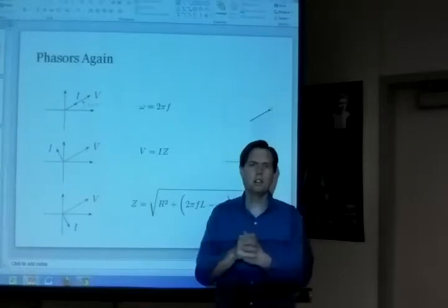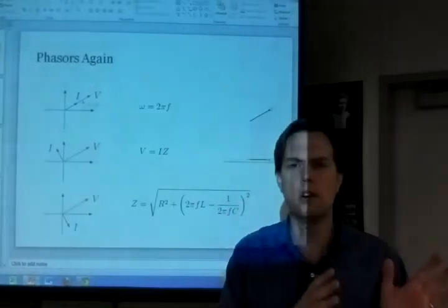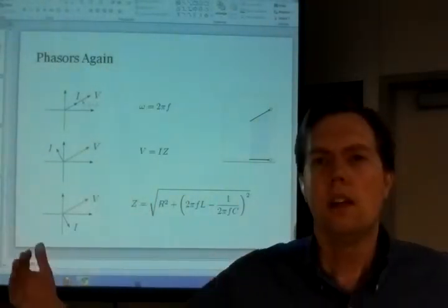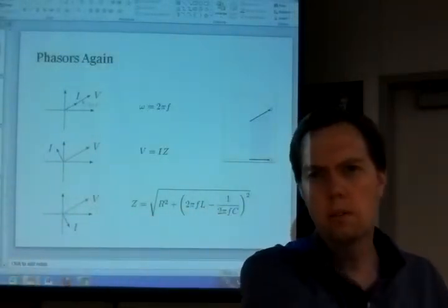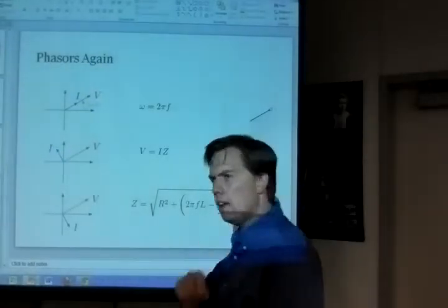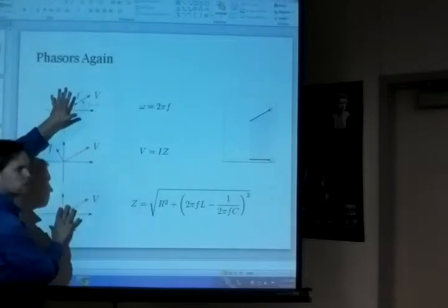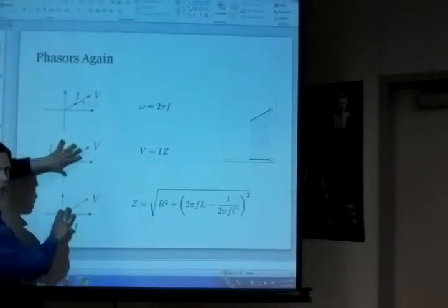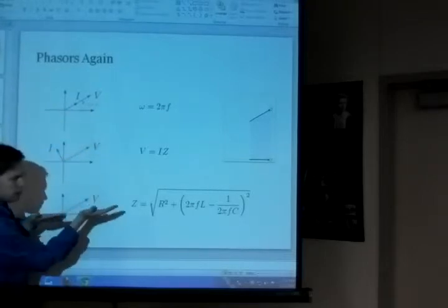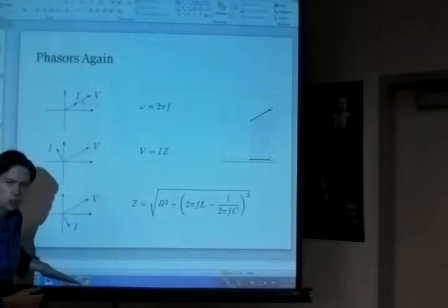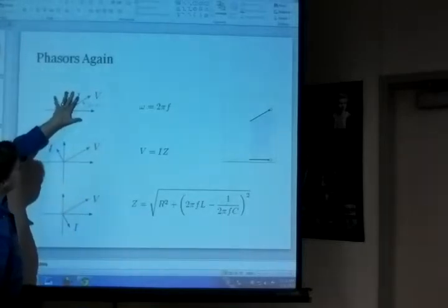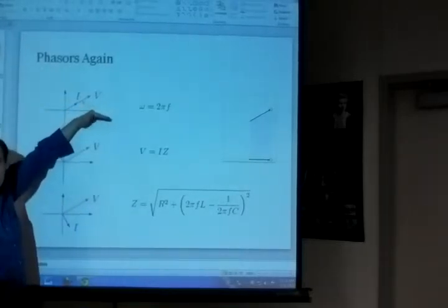So the way it will work is that suppose we have a simple RCL circuit, a series circuit where we've got a resistor, capacitor, and inductor. The current flows through all three components because they're in series. So whatever current flows through one flows through the other. Which means that we should take these three pictures and twist them so that the current is all lined up, is all pointed in the same direction, because the currents are equal for our three components. And in fact, it would be even simpler if we took this and twisted it so the resistor were completely horizontal. So that's what we do.